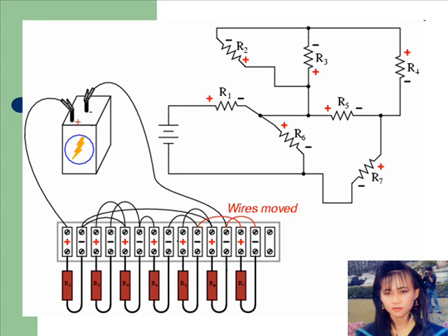it might cause confusion for anyone measuring resistor voltage drops with a voltmeter, especially an analog voltmeter, which will peg down scale when subjected to a voltage of the wrong polarity. For the sake of consistency, it might be wise to arrange all wire connections so that all resistor voltage drop polarities are the same, like this.